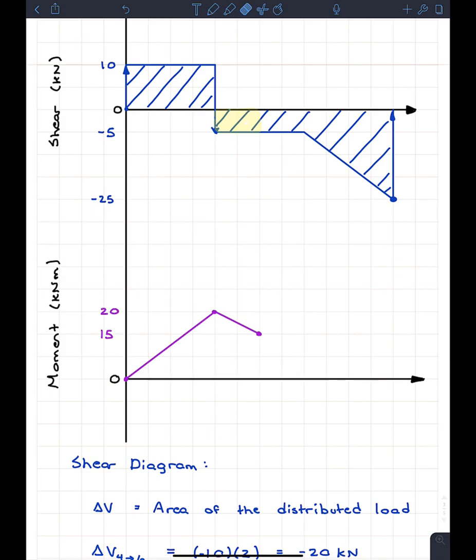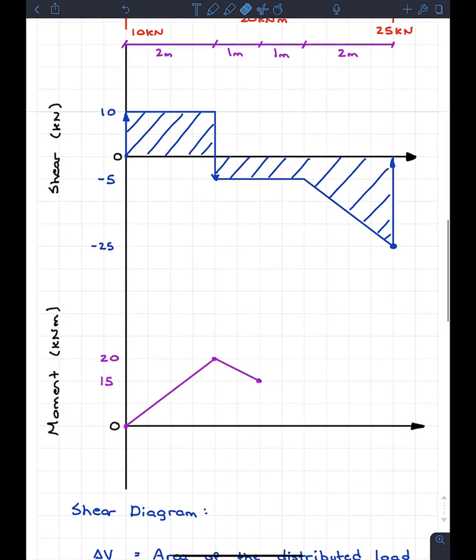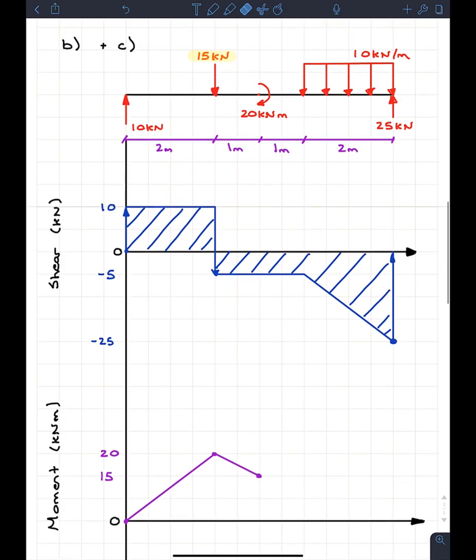But now we have something that we can't really predict with the shear force diagram, but rather we have to go to the free body diagram. And that's this thing right here. And it's very important to watch out for these because professors love them. It's these concentrated moments right here. And the reason why professors love them is because they have the same effect as concentrated loads.